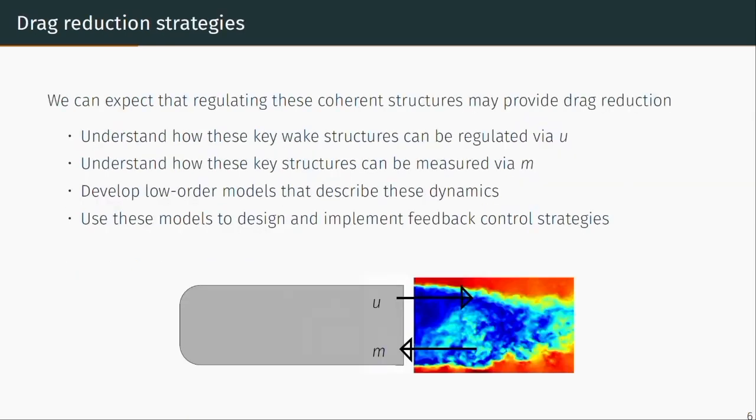Given that these three-dimensional turbulent flows have these particular coherent features, and that these features can, in some ways, most likely be related to the drag, we targeted an approach in which we hope to regulate these particular coherent structures in the turbulent wake, in the hope that this leads to a drag reduction.